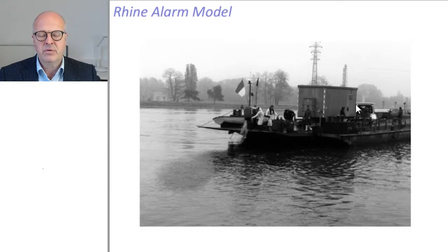Once this breakthrough curve was measured, an advection dispersion model that I will develop in the next slides was fitted to these experimental data, which was a huge reduction of data, because instead of all these data, you could reduce the model to just 2 parameters, and with these 2 parameters you could predict the breakthrough curve, travel time, and concentrations for pollution events of any magnitude for that section.